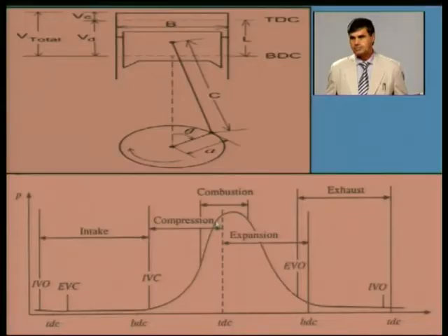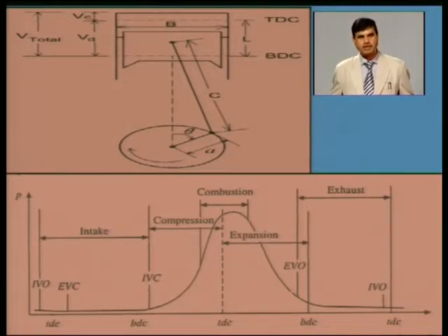After compression, without combustion, just compressing, say with a compression ratio of 8 in a petrol engine, roughly after compression we are receiving around 10 bar. In the case of a diesel engine where the compression ratio is 15, after compression, without combustion, just compressing air, the pressure which we are getting is around 38-39 bar, 40 bar.